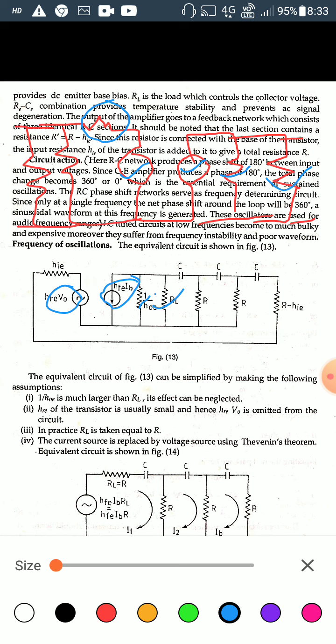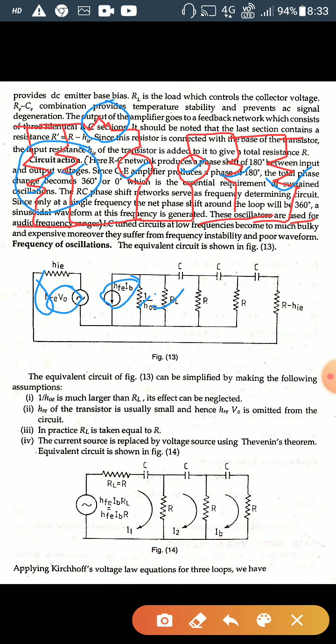And here the other two resistors are R1 and R2 for the biasing. Why are they not used in this position? Because the circuit combination is chosen in such a way that the parallel combination of R1 and R2 works as a very high impedance. If it is so high, it can be treated as an open circuit, so you can omit this section.